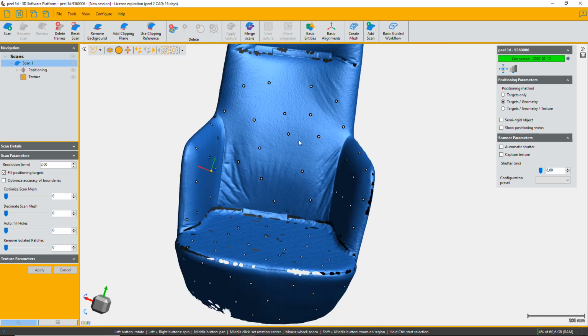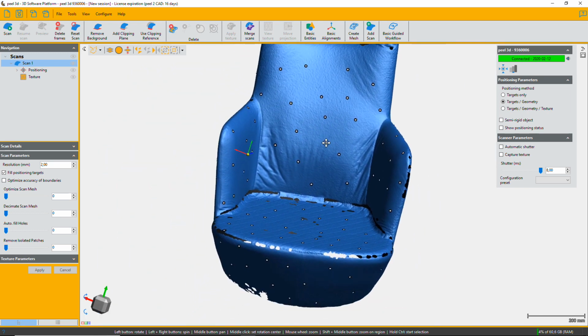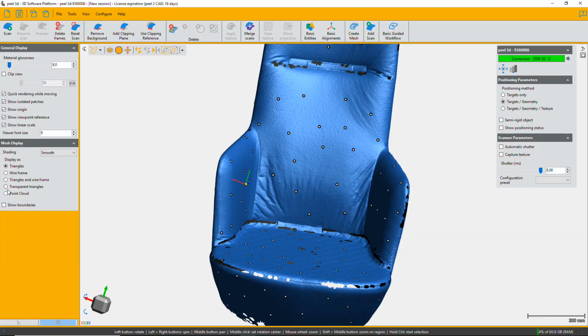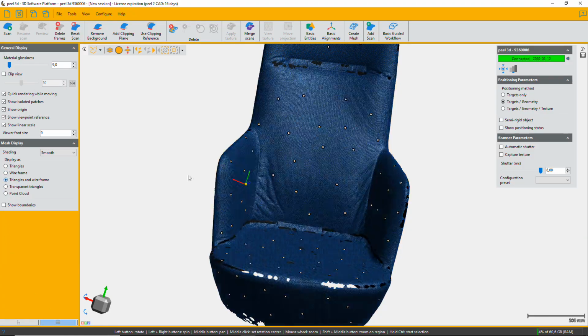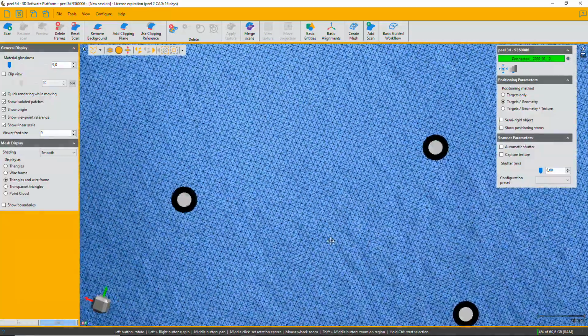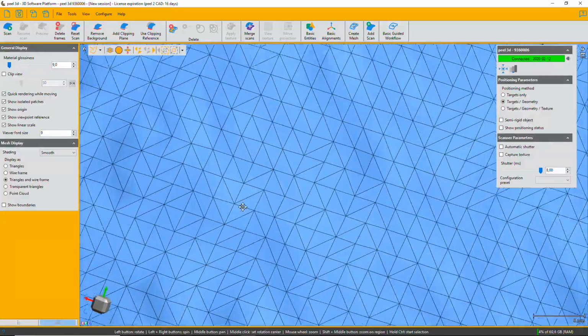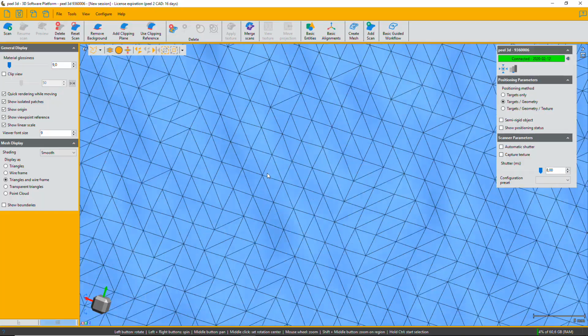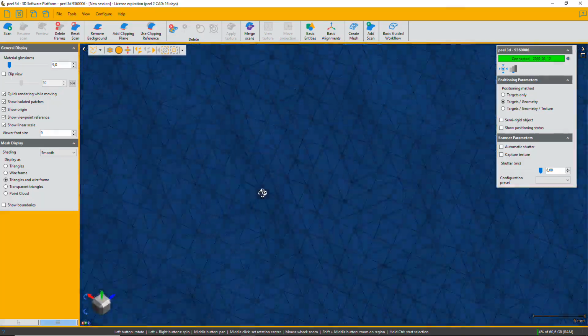So you mentioned 2mm resolution. Can you just talk a little bit about resolution, high versus low, and sort of optimal? Pierre's going to turn on the mesh, and I'm going to show you the mesh that's associated with that surface. And we're going to zoom in because it's a lot of triangles. Keep zooming. So that's your mesh. It's a very dense mesh. In fact, you don't need it that dense.